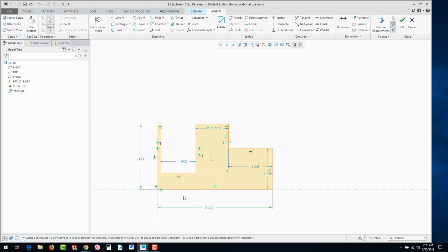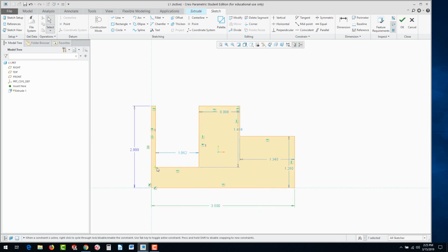Now you'll see it will truncate. It could even intersect geometry by accident. Sometimes you'll get something like that, and then the shading disappears. The shading is an indicator that it's ready to go because it's a water-type boundary condition. Once you get something like this and the shading disappears, you've got to fix it. So just drag some of these points and get them to look similar to what you want. Look at that. You can grab the lines. I'm not in any tool. I'm just dragging them with my pointer and my mouse button pushed down.